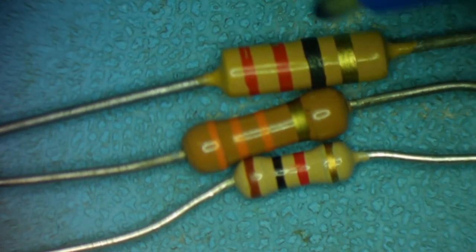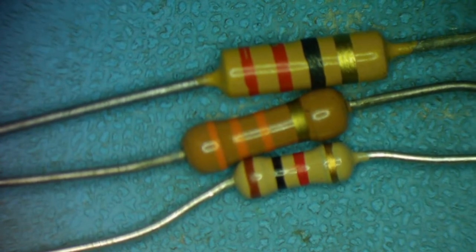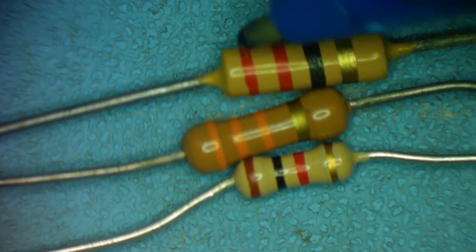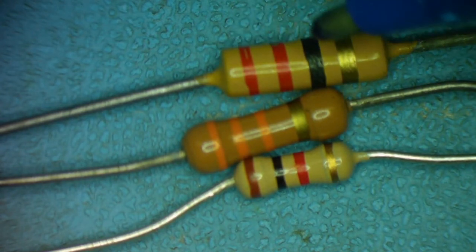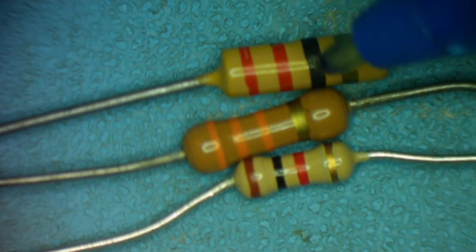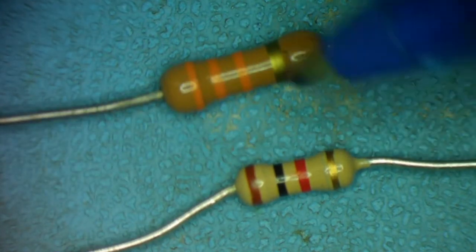Because when you make a resistor, it's not exact. So they come like, you know, the value it says plus or minus 10% or plus or minus 5%, yeah. So just look at these now. We used to look at these. So we go red, red, black. That's 2, 2. Black is 0, and the third one's the multiplier. So that's 2, 2 times 0. That's 22 ohms. Yeah.